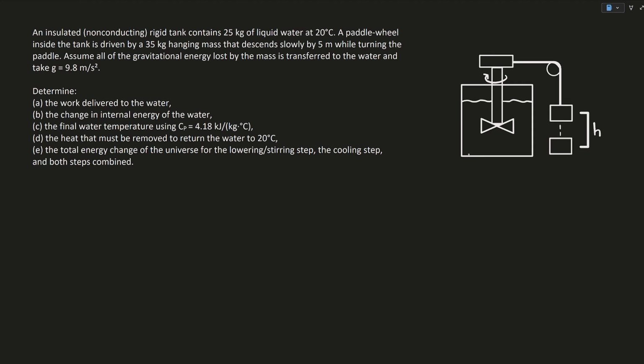This is a closed system, meaning that mass does not cross the system boundary, and the tank is insulated, meaning that there is no heat transfer. So our heat Q is equal to 0. The paddle does work onto the water directly, which increases the water's internal energy.